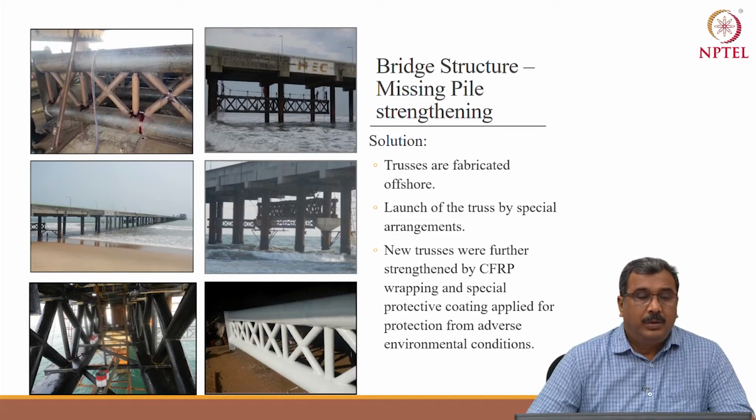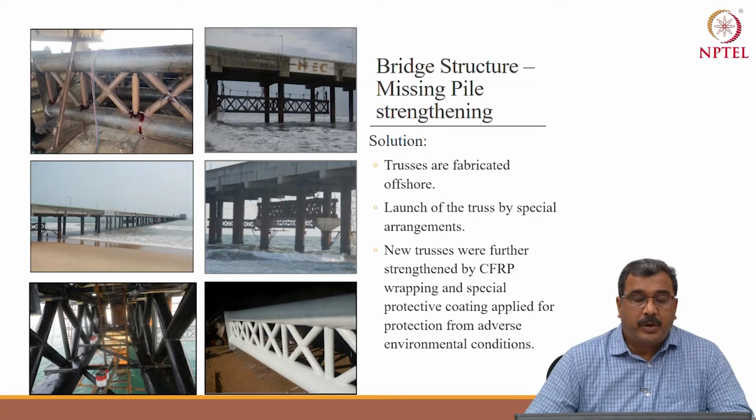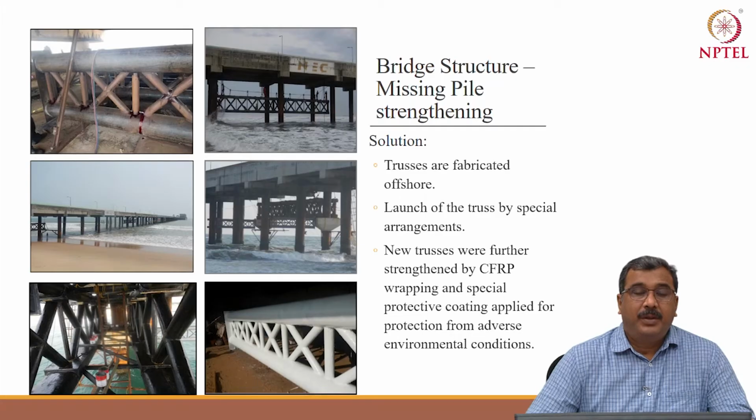So, your brackets are in position, the truss has been put in position, protected properly, then jacked to take the load of the pile. So it is properly transferring load exactly on P20, not on P19 and P21 as it was doing when there was no pile. And proper deflection and loading checks have been carried out at location.